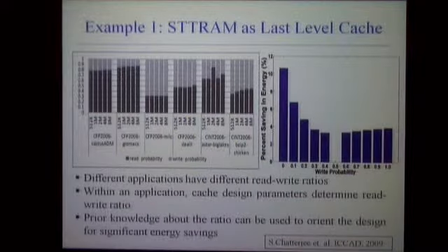So if we look at the diagram towards the left, what we see is that the best case comparison cell is designed at a write probability of 0.5. And as the write probability reduces in this zone, and these are cases which are read intensive, my percent savings in energy increases because these have been optimized for a low write probability. So the point is that if we can somehow have a good estimate of the write and the read probability of this application, then we can accordingly modify our cell design in order to achieve a more energy efficient cell.